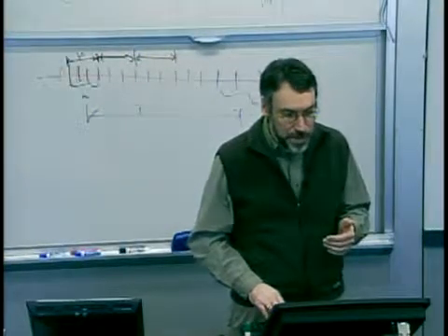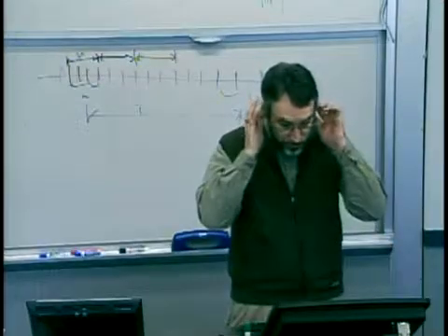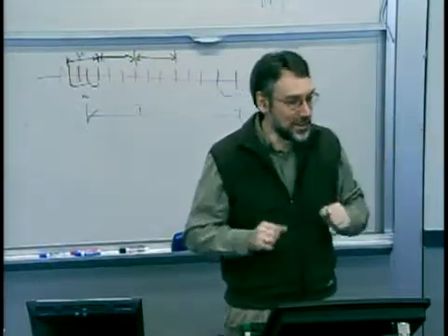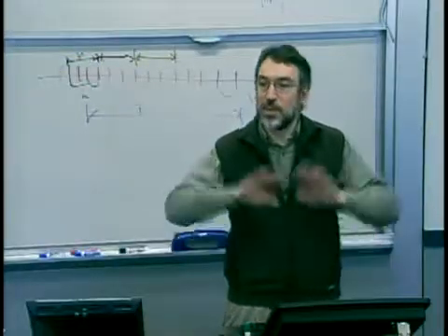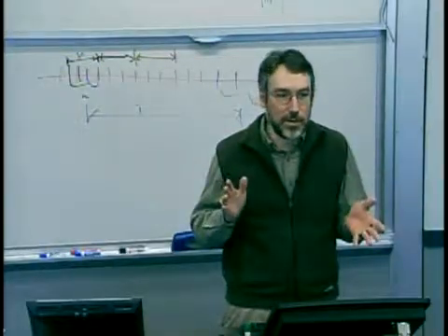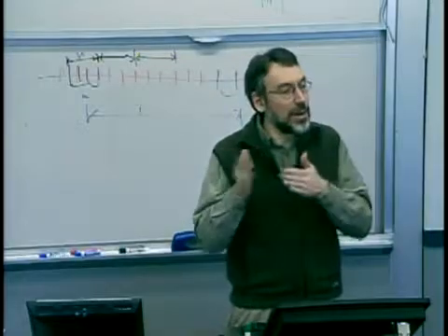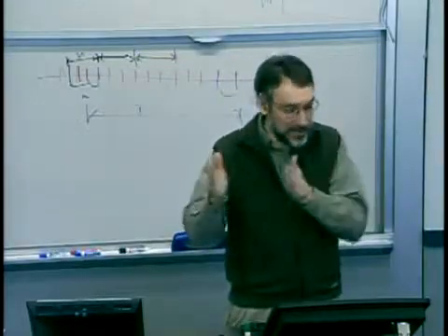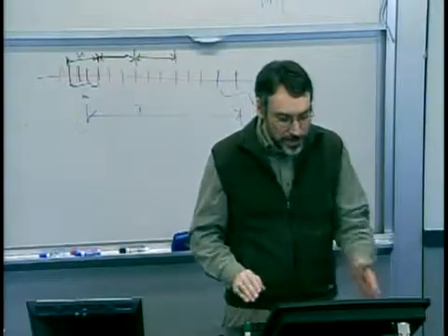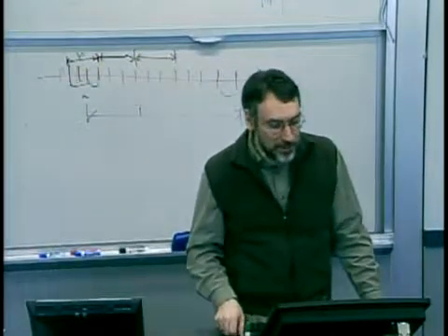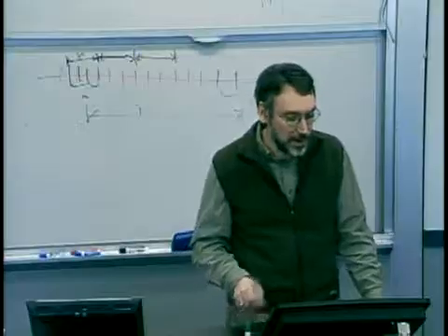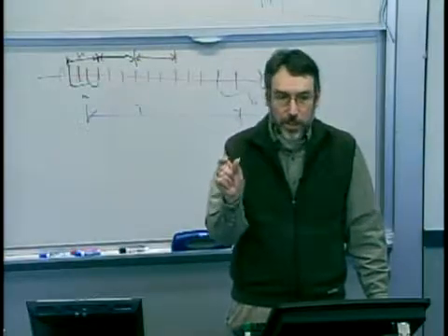But the basic idea, and this almost goes back to your earlier question, imagine first off what we're doing with just a regular X-bar chart, but where we're measuring every part and then just aggregating in samples of different size. So what I've got here is the run data, and then in the little purple pictures is an X-bar calculated for each group of 4 sample points.